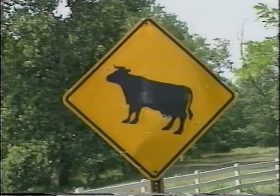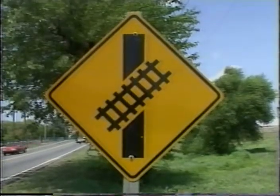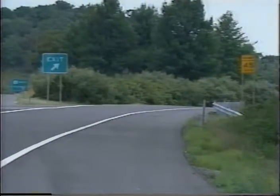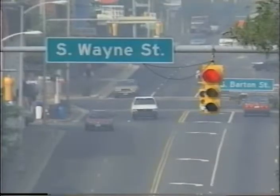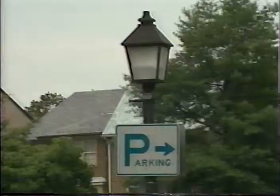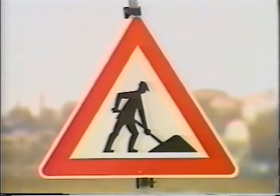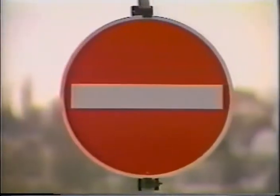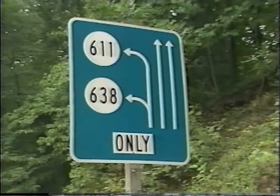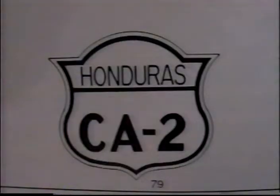Warning signs alert drivers to hazards such as narrow roadways, railroad grade crossings, and slippery pavements. Guide signs provide directional information such as destination names, route markings, street and highway names, parking, and general services. Specific elements are applied to the design of traffic signs to assist with driver understanding of the intended message. The design elements of each system are color and shape.